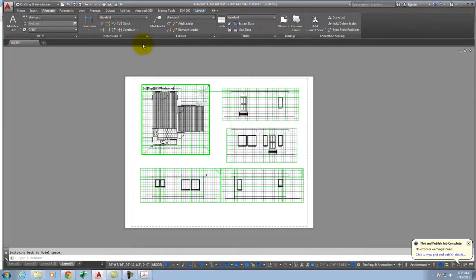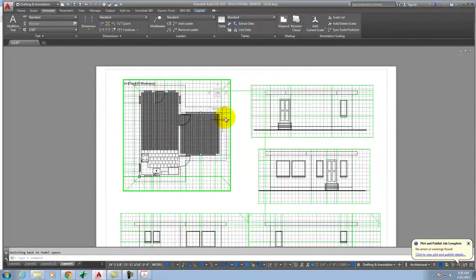So in general, in my own AutoCAD practice, I would set up drawings like this with any dimensions that needed to be on the page, but without any primary text, because I'd like to add that in Illustrator afterwards. So I'll show you how I do that. I try to get all the line weights correct. I try to get the general layouts correct. And then I deal with title blocks and all of that stuff in the world of the Adobe products, whether it's in Illustrator or in InDesign after the fact.